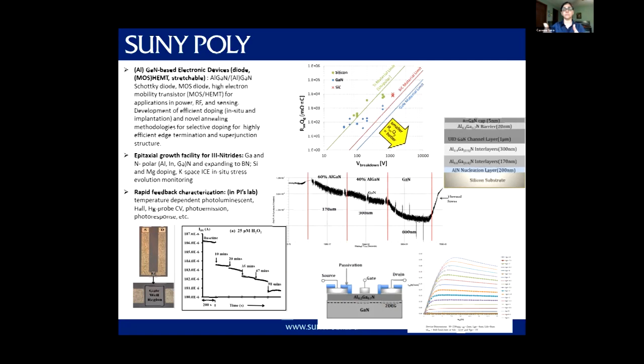The rest under it is really stress engineering, because you're putting together layers that are highly lattice mismatched. Think about having two atoms and putting something much larger or much smaller on top of it. As you make it thicker and thicker, it creates cracks or a lot of stress. So the rest of it is doing stress engineering.